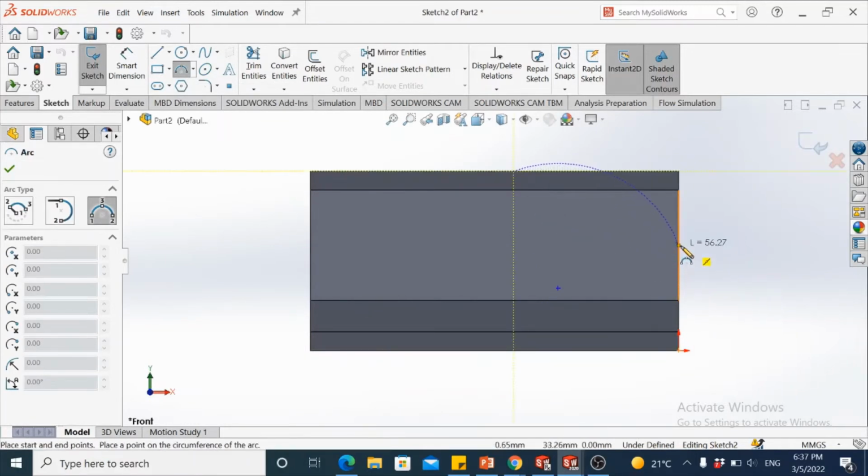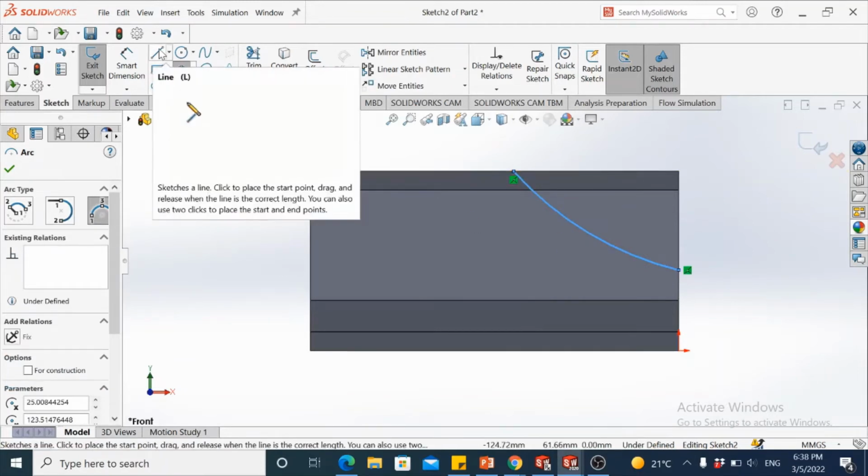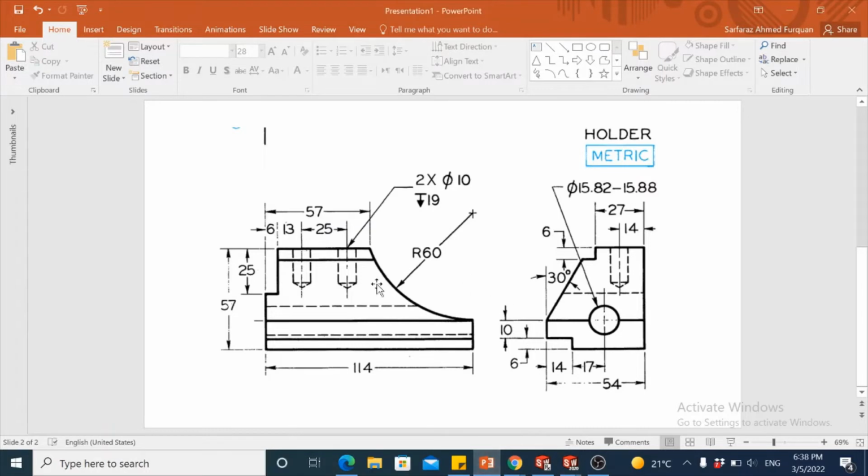Make sure you do not drop it onto the midpoint here. It gets constrained, so leave it coincident with the right edge. Let it get defined with the radius. There's another slot that we can cut out simultaneously, as can be seen here.